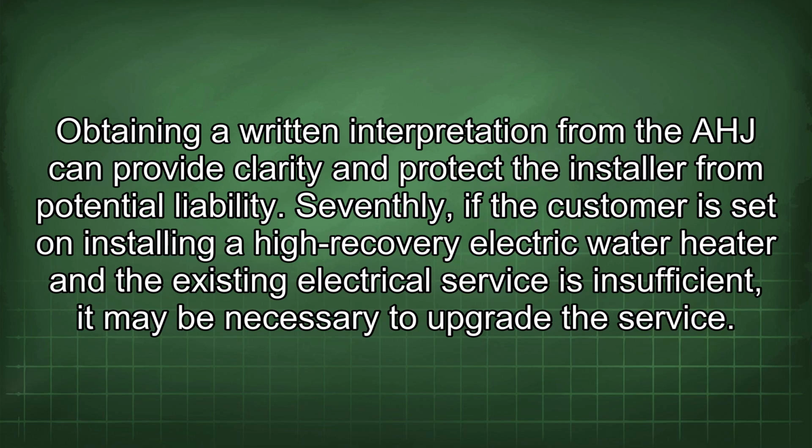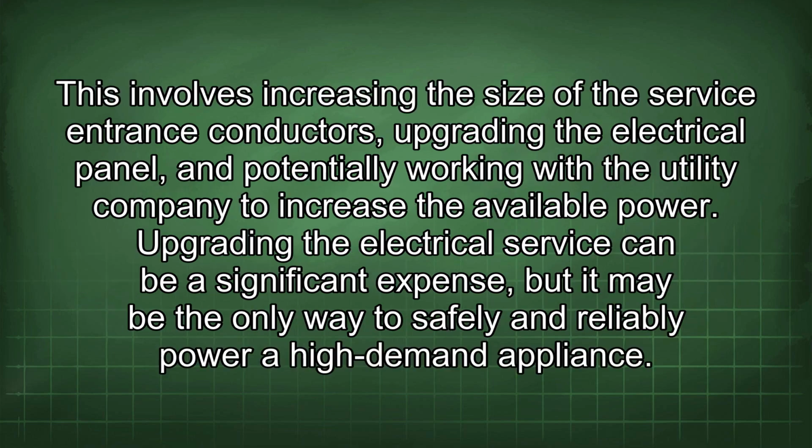Seventhly, if the customer is set on installing a high-recovery electric water heater and the existing electrical service is insufficient, it may be necessary to upgrade the service. This involves increasing the size of the service entrance conductors, upgrading the electrical panel, and potentially working with the utility company to increase the available power. Upgrading the electrical service can be a significant expense, but it may be the only way to safely and reliably power a high-demand appliance.